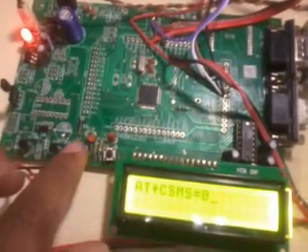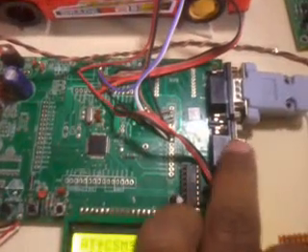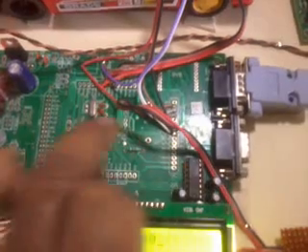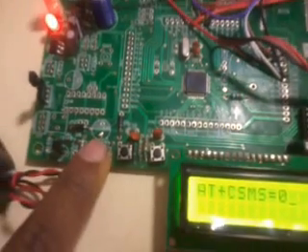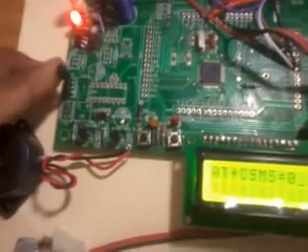In this development board we have 2 switches, one called ISP and another called reset. Whenever we want to dump the program onto the microcontroller using UART 0, we must press the ISP continuously, then press and release the reset. Here we have 2 transistors, used if you are going to drive a fan, an engine cooling fan or an alarm system, for which we use the buzzer. This is the LM35 temperature sensor and the MQ2 gas sensor.